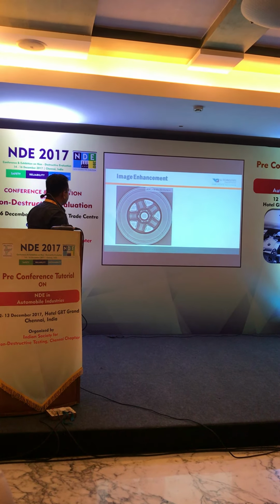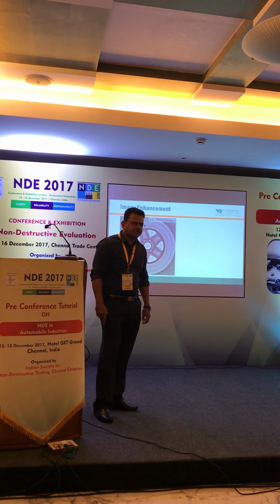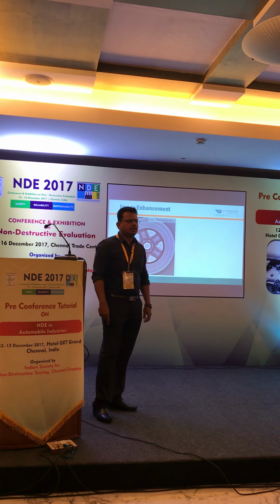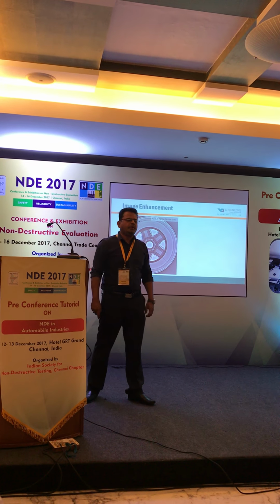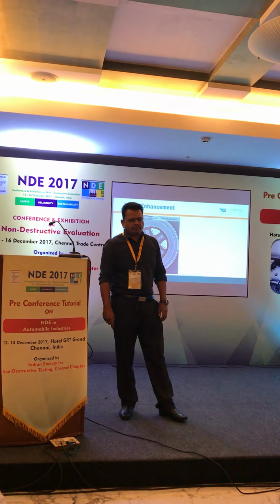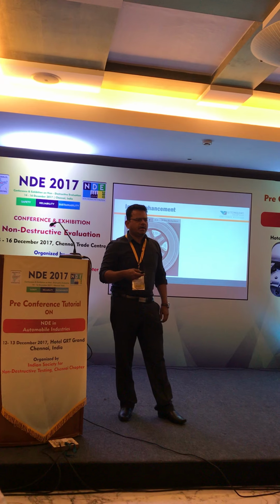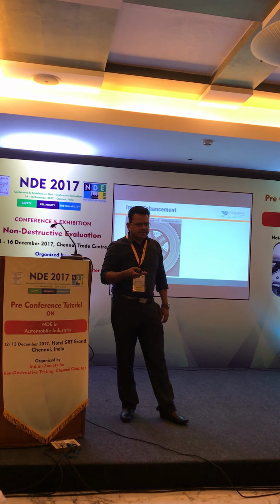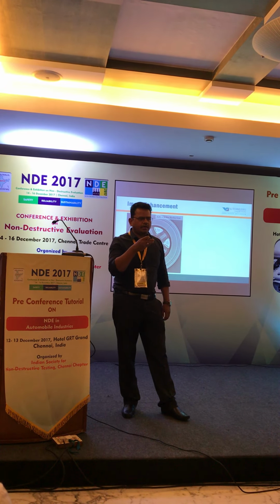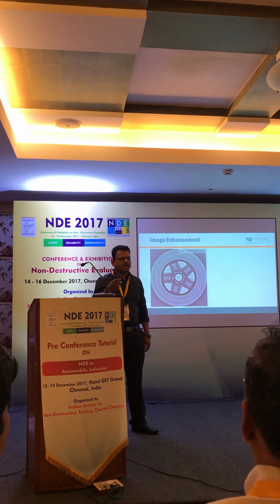So in digital radiography, we have signal to noise ratio, contrast to noise ratio, and what we call spatial resolution. Say the automated machine runs 24/7, and we can do a periodic detector performance test after one week or 10 days to see whether the spatial resolution of the detector will pass or fail, because we need to achieve 2% sensitivity on that particular detector.